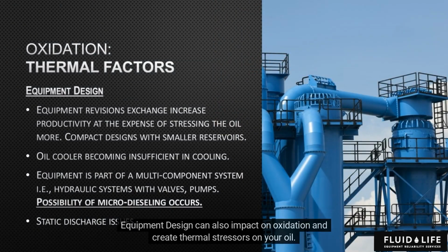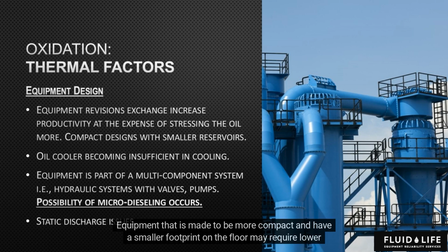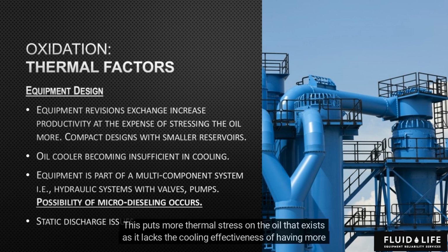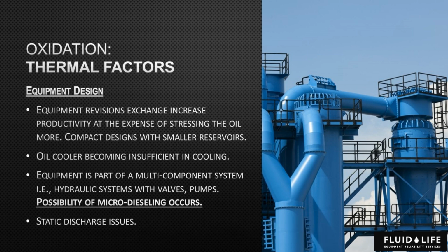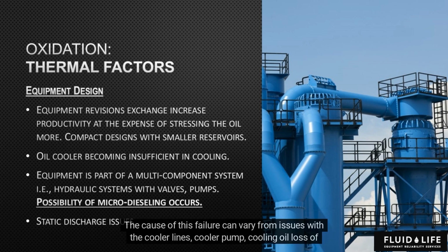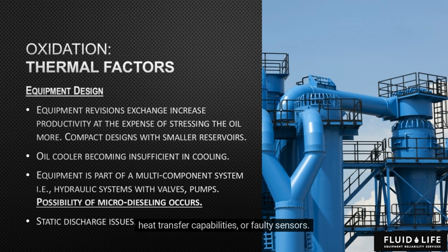Equipment design can also impact oxidation and create thermal stressors on your oil. Equipment that is made to be more compact and have a smaller footprint on the floor may require lower volume sumps or reservoirs. This puts more thermal stress on the oil that exists as it lacks the cooling effectiveness of having more volume. Another equipment design issue could be that the oil cooler is insufficient in cooling the oil. The cause of this failure can vary from issues with the cooler lines, cooler pump, cooling oil loss of heat transfer capabilities, or faulty sensors.